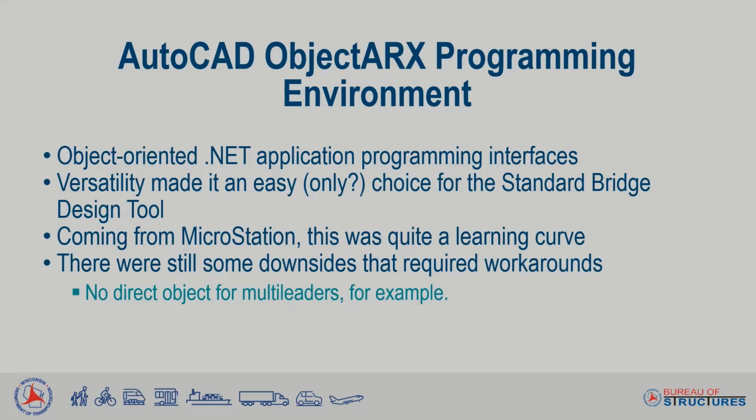The AutoCAD ObjectARX programming environment is what I use to develop the standard bridge design tool. It has object-oriented .NET application programming interfaces, or APIs, and its versatility made it an easy and possibly the only choice for the standard bridge design tool. Coming from MicroStation, this was quite a learning curve. There were still some downsides that required workarounds. For example, there was no direct object for multi-leaders.